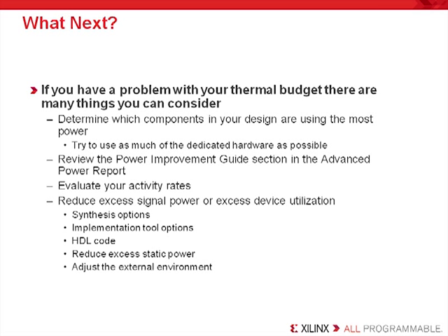At this stage in the development cycle, the printed circuit board is already being designed, and the voltage regulators, cooling devices, and other device environment properties are set, so changes you can make in this area are often restricted. It may, however, be possible to supply more cooling or lower the supplied voltages. So these are just a few of the big ideas that can be used to help you resolve a power problem.